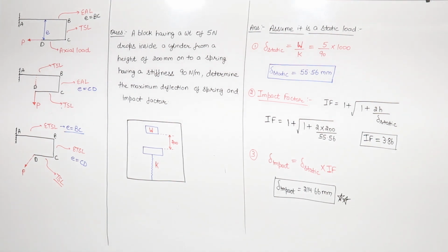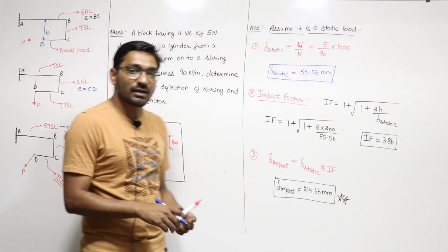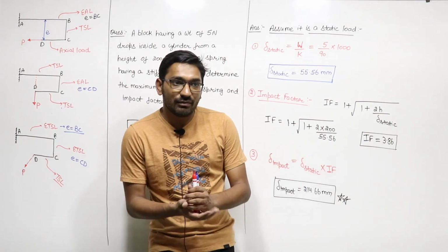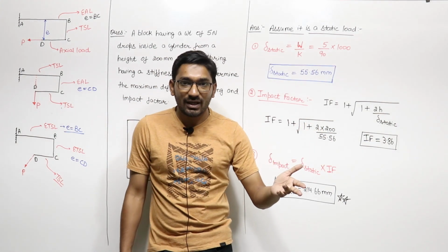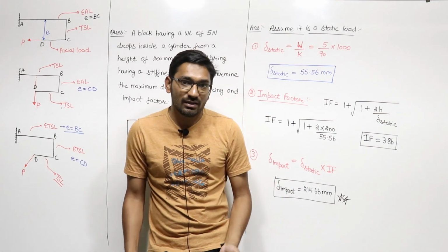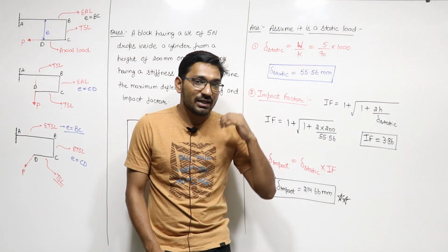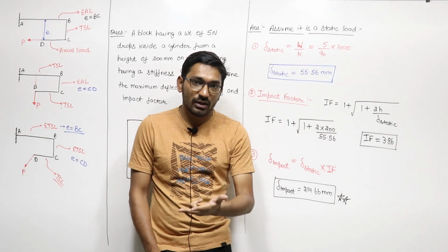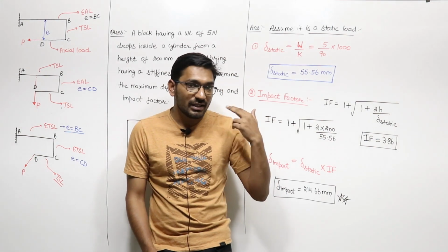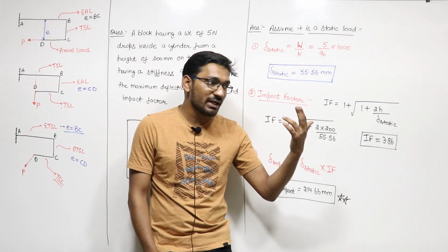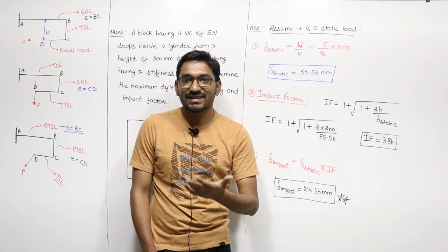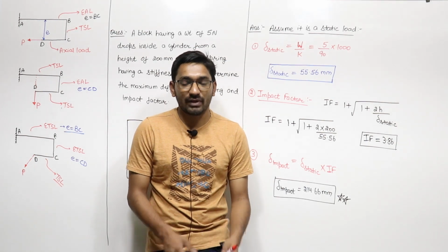This is how you can identify any load with respect to the longitudinal axis. By seeing the nature of the load with respect to the longitudinal axis or the plane of cross section, you can identify whether it is a normal load or shear load, and in normal load whether it is axial or eccentric axial, and in shear whether it is a transverse shear or eccentric transverse shear.